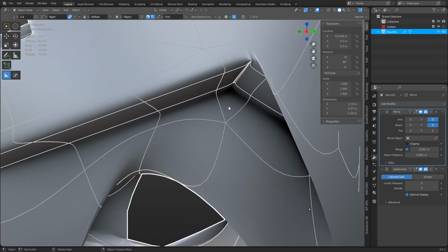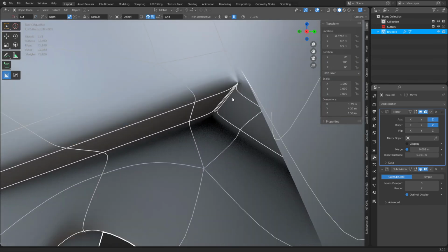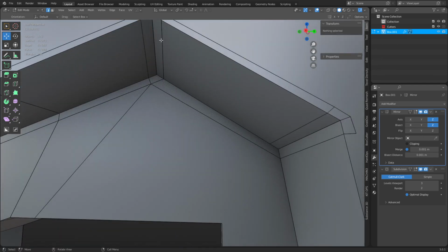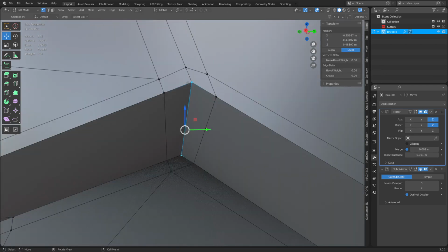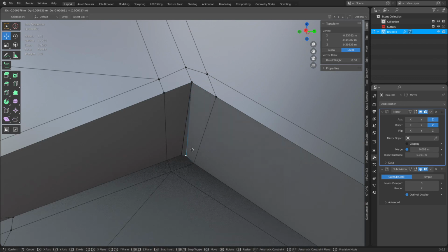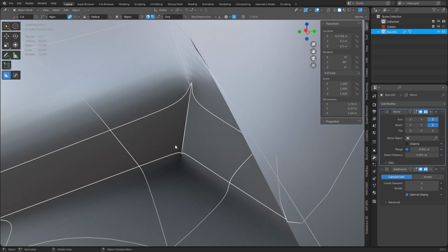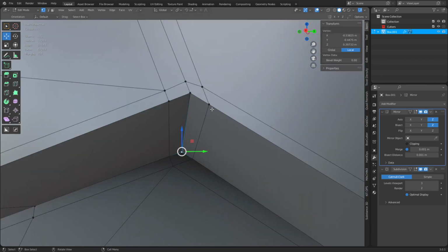You can look at the subdivision result, see if you've got issues popping up. A lot of times it points it out for you. It's a double edge or a double vert in here. That's all it is, the double vert. We'll move one, grab the other, hit it with machine tools, do a smart vert or merge at last, basically. You see that one worked itself out. This one's still not good there. Okay, so it should be good now. Oh, still not good.